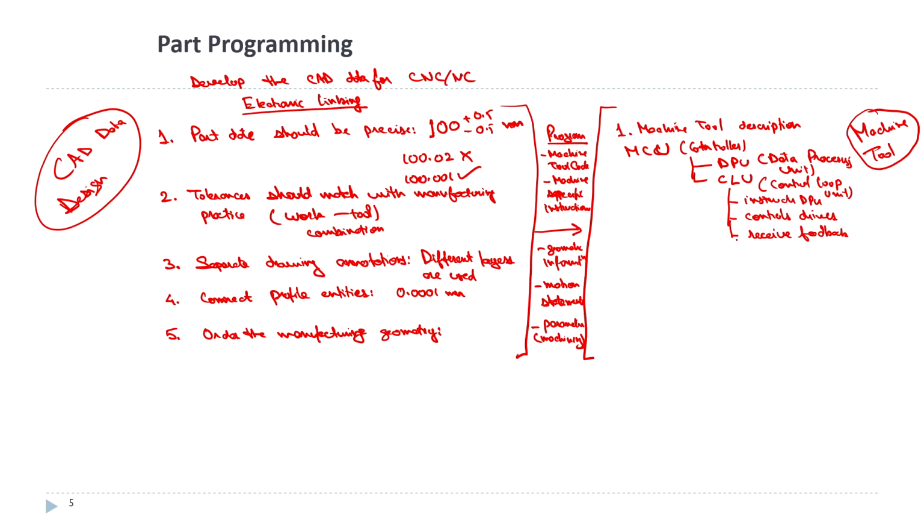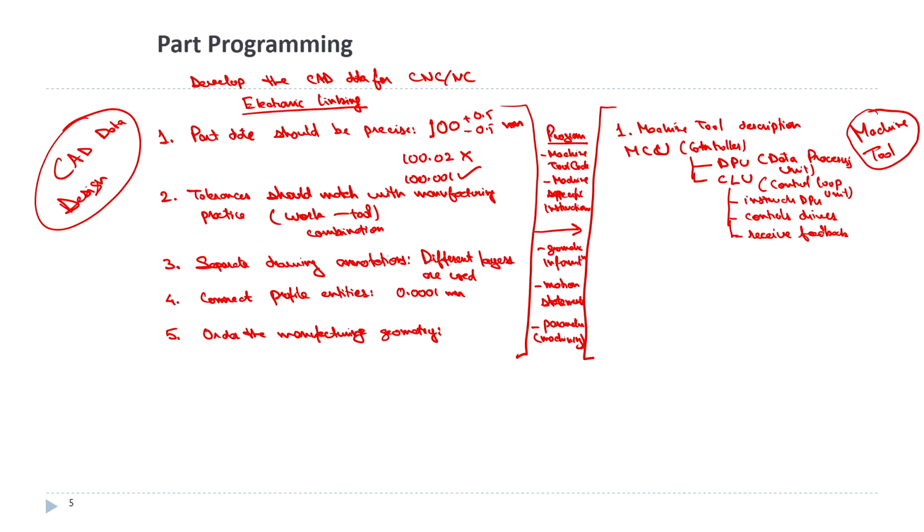So, to design the machine, each axis has its own lead screw, control signals and its feedback control. That is for sure, because each axis has to move independently. So, this becomes our second part of the machine tool characteristics, that is, the axis of the machine.